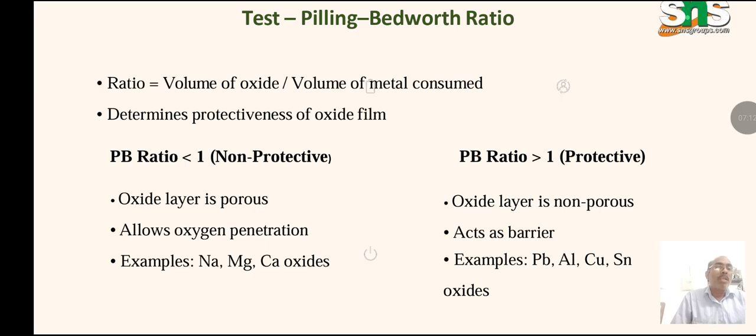It determines the protectiveness of the oxide film. A Pilling-Bedworth ratio less than 1 is non-protective; a ratio greater than 1 is highly protective.